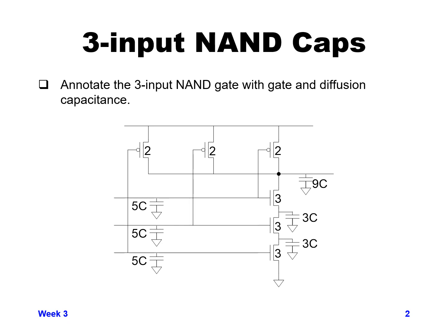This compares to if we had a single inverter with a size 2 PMOS and a size 1 NMOS. Our input to a single size inverter would be only 3C instead of 5C for each of these inputs, and the output would only be 3C instead of 9C, and then having an additional 6C in the pull-down stack.